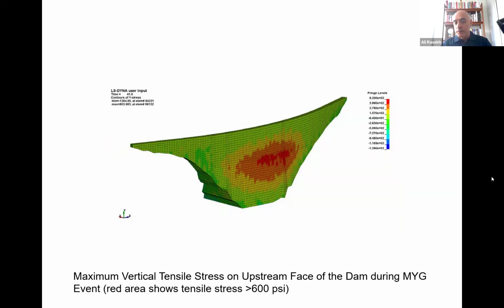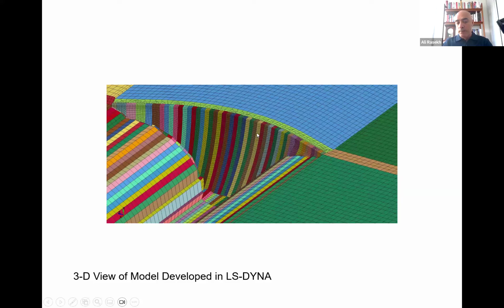Why do they put multiple layers here for the dam? As I said, you don't call them layers because they are vertical. They are vertical joints. And as I said, this is real: on the dam, this red and this yellow are separate. They are two different parts, and we want to build them as such. I forgot what concrete technique they were using, but whatever it was, we want them to be separate, because in winter they should slightly separate from each other and not cause tension.